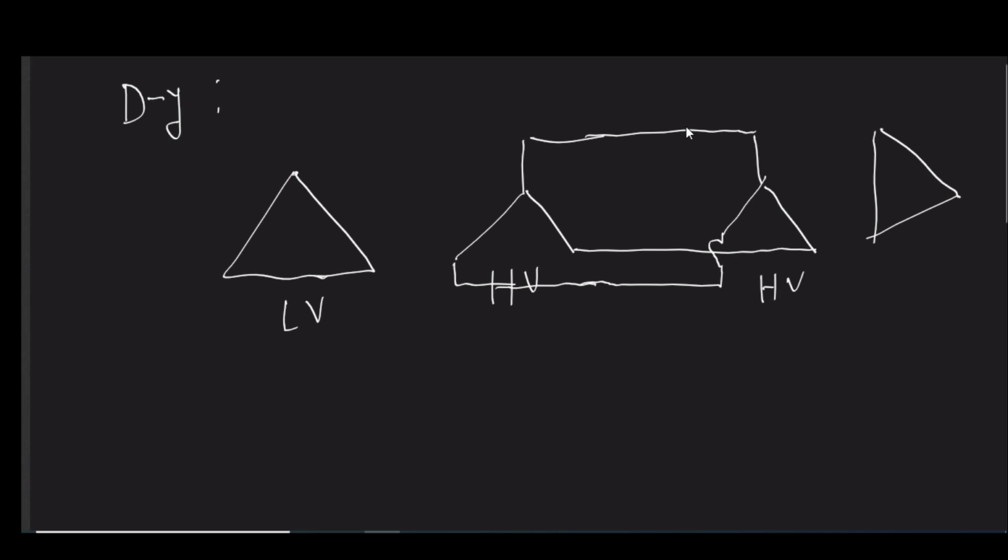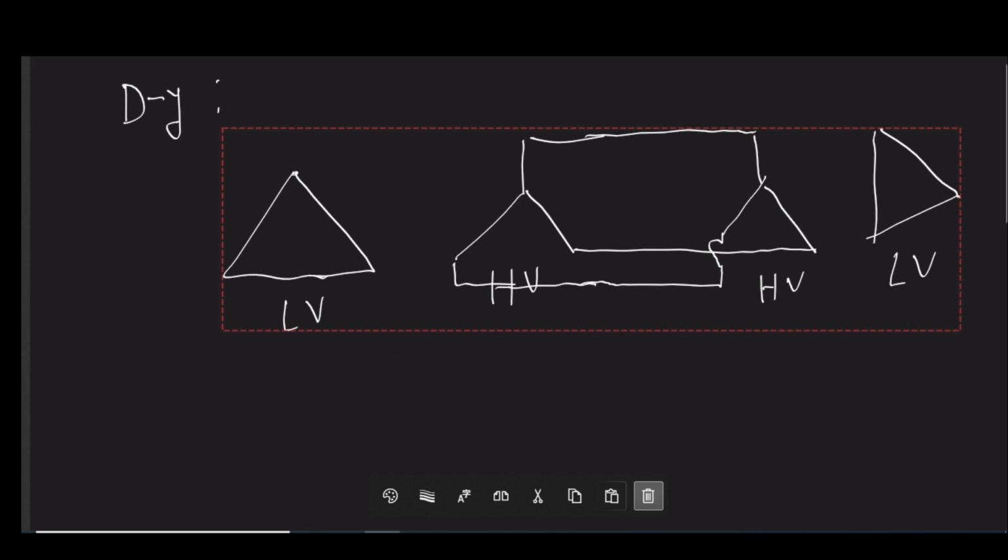Then again you receive at high voltage, and then you step down to low voltage and make it delta, because whenever you want to step down you have to consider a flow of high current through your winding, because kVA cannot be altered, right? So if you want to keep kVA constant, then for low voltage you must have a high current flow through your winding. So for delta-star, what is the case?